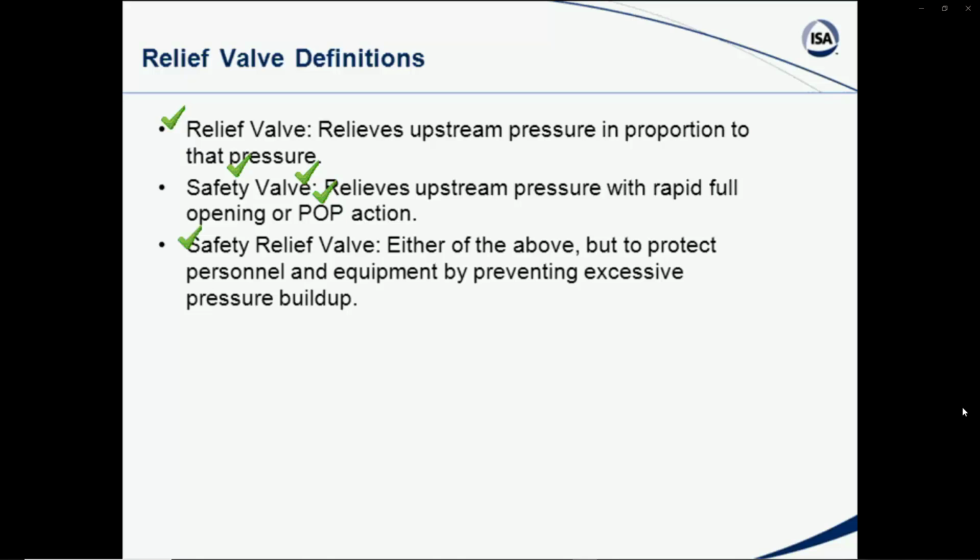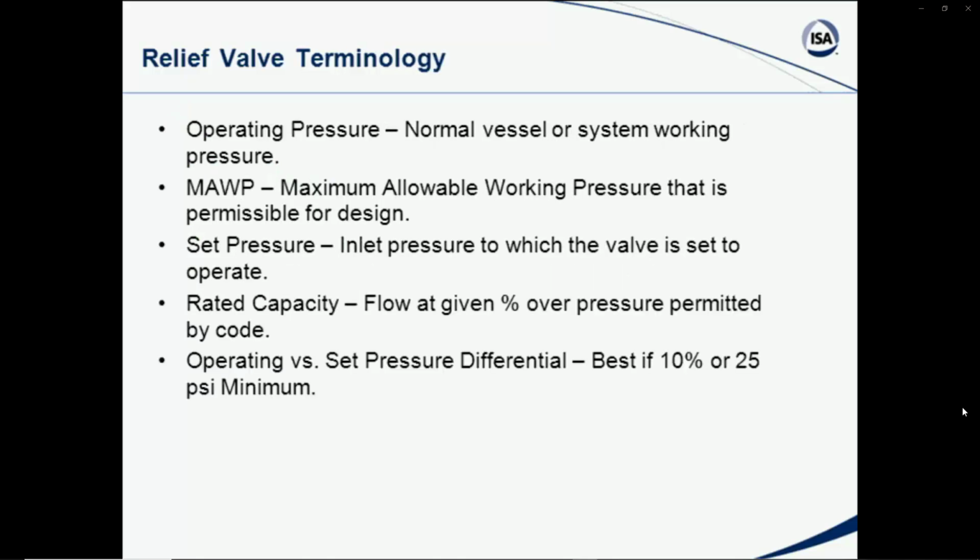In other words, one terminology is a pressure reducing valve, which can be a self-contained modulating pressure reducing valve, or a safety valve that has pop action, or, if you actually have personnel and equipment endangered, that becomes a safety relief valve. So it's all sort of some of the same terminology. It depends on exactly how you look at it, how you count your words.